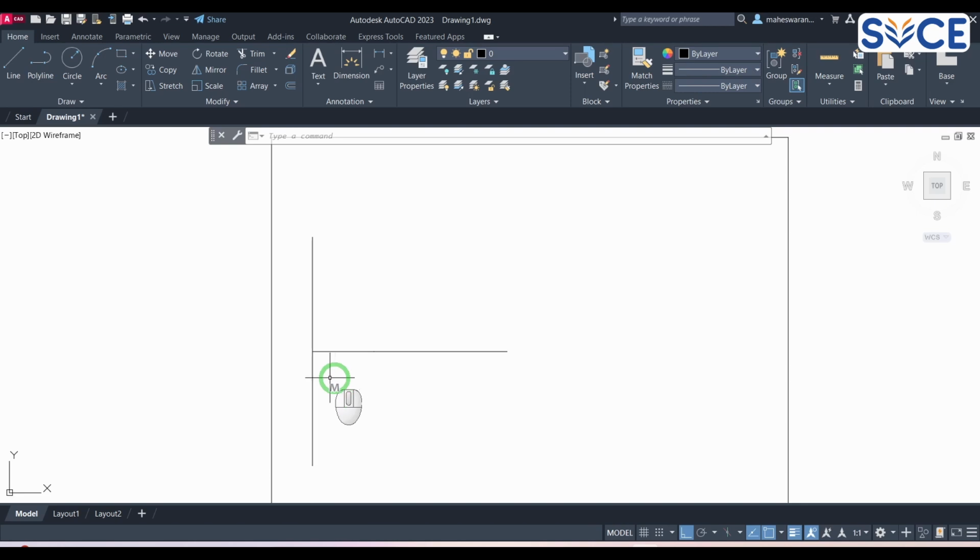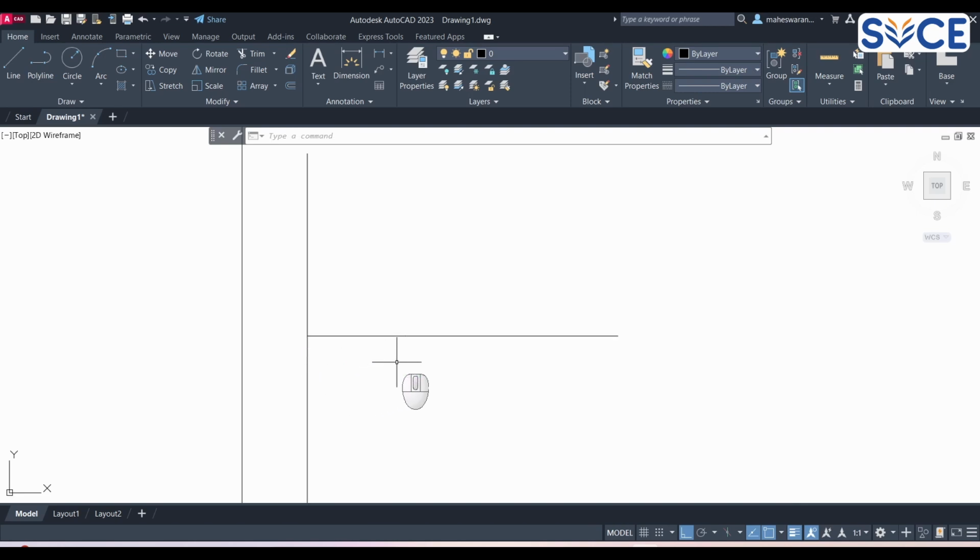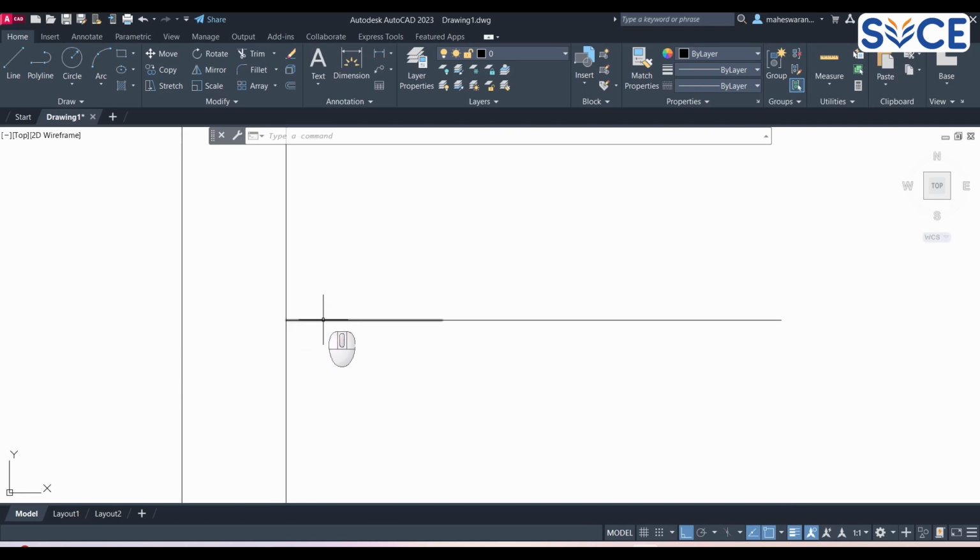So now the next step, as per our regular procedure, is I want to divide this line into equal parts. You know the eccentricity is 3 by 2. So your numerator is 3, denominator is 2. So 3 plus 2 is 5. So I have to divide this into 5 equal segments.